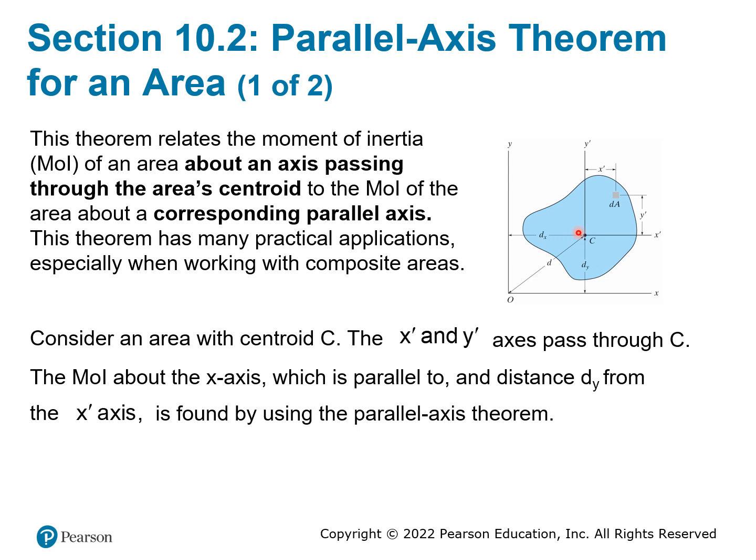And so we want to find out in which way you have a larger or smaller moment of inertia. So you have to look at how far the object is away from the axis, because it will create a different amount of moment. There are two kinds of moment of inertia of the area, and one is simply about x and y. This corresponds to the Cartesian coordinates. So if you have a two-dimensional shape like this, you have an x-axis and a y-axis.